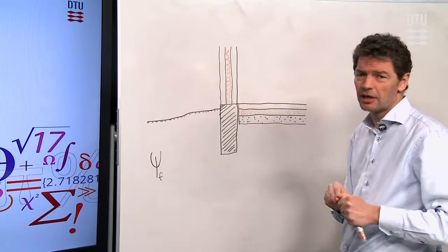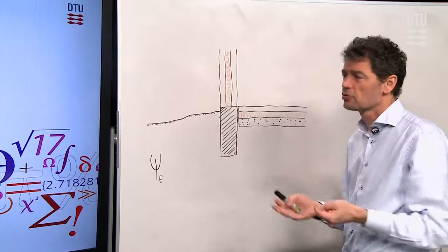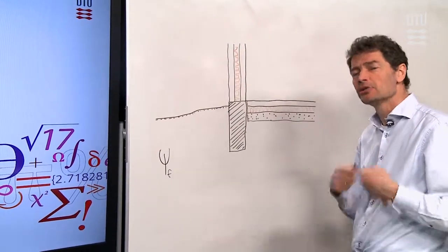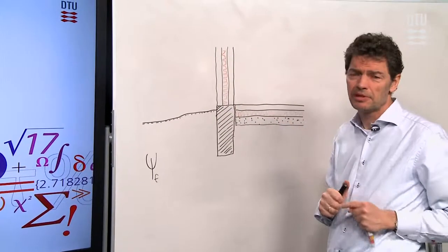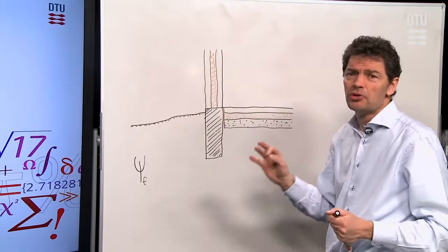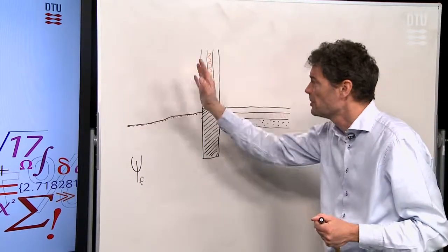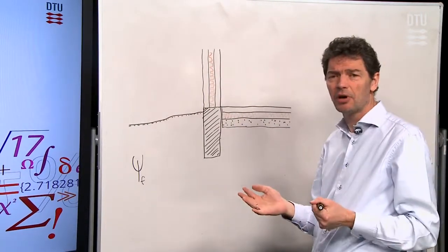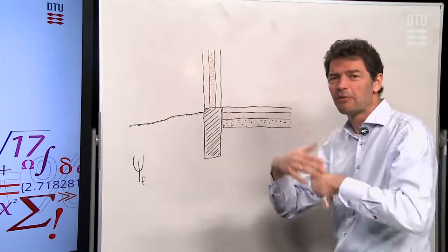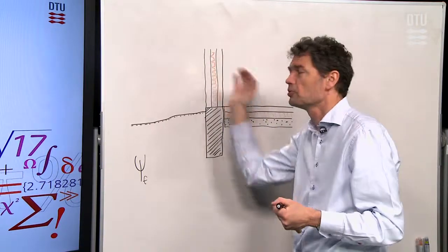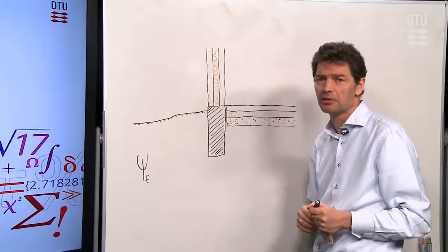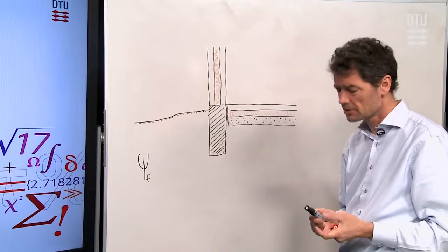The methodology normally says that you have to use a multidimensional heat flow calculation program to analyze the total heat flow through the multidimensional construction that you have. And then you subtract from that normal one-dimensional heat flows, which you can see are involved in the process, and the difference between the accurate way everything is calculated and the simple way with only one-dimensional flow becomes the thermal bridge and can be put down in numbers like the psi value, for instance.